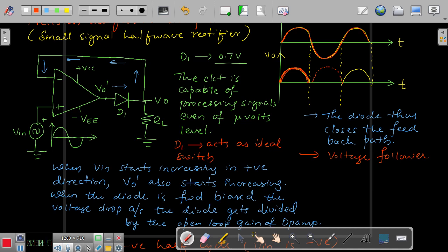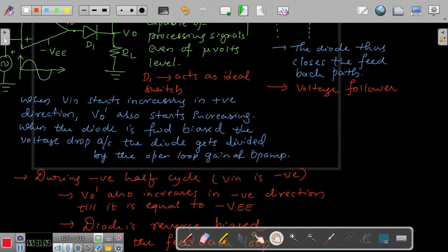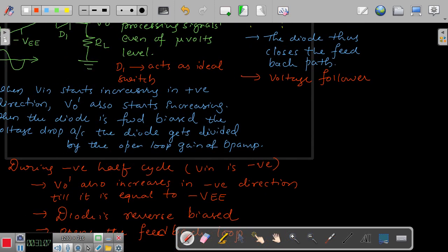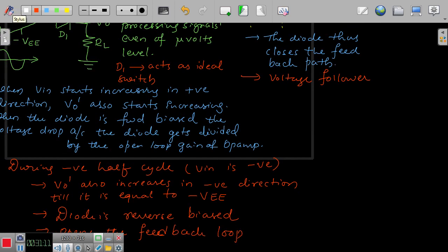You have to make the charge carriers recombine. Negative voltage should come across the diode, then it will become completely reverse biased. There are so many other conditions to be satisfied in making the diodes become forward biased and reverse biased. Therefore, we will not be able to use the conventional diodes here, what we use in our conventional applications.